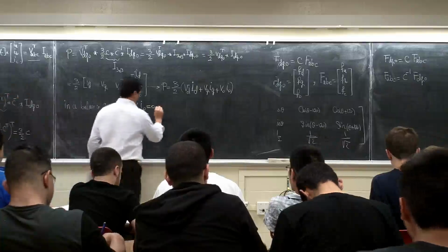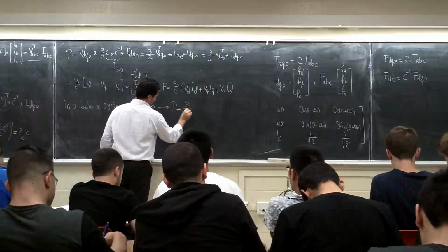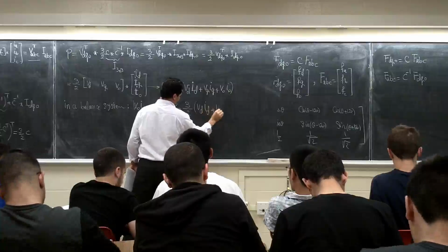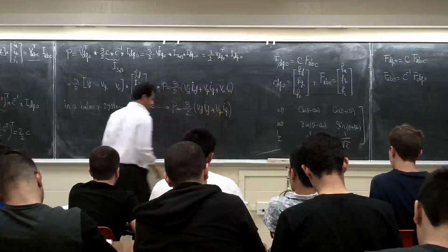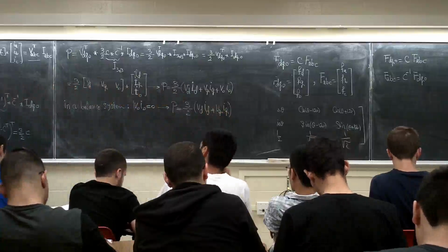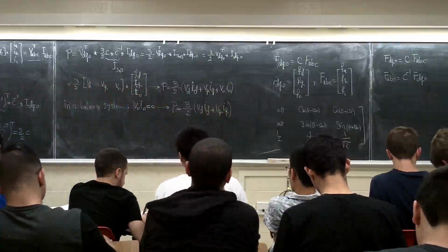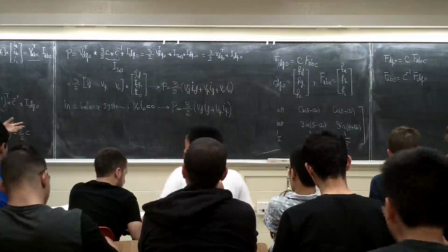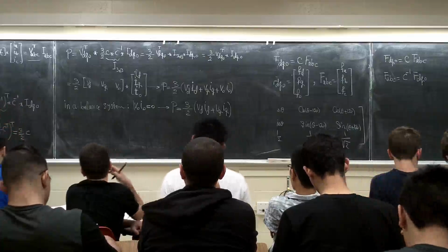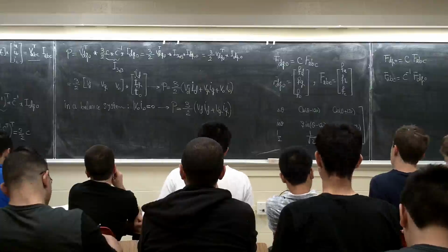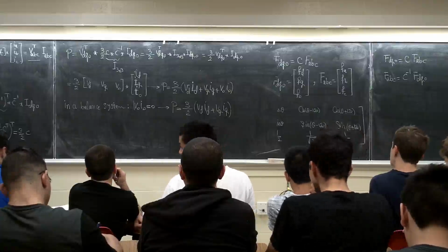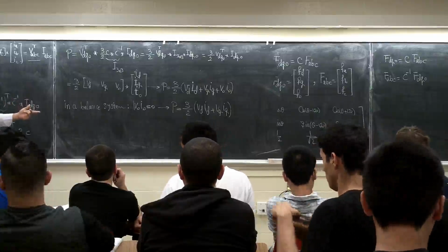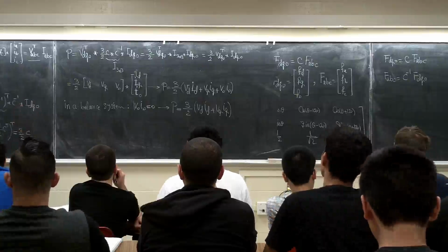So basically P is equal to 3 over 2 times VD ID plus VQ IQ. In an unbalanced system, that becomes a three-phase quantity, still a DC value, you know. You're not going to see the unbalanced system in this class. But when you simulate this one and do some homework, put in a little bit of imbalance, you can see what happens when you're doing the simulation. If you're curious, make it a little bit unbalanced to see what you're going to see. But usually systems are balanced.